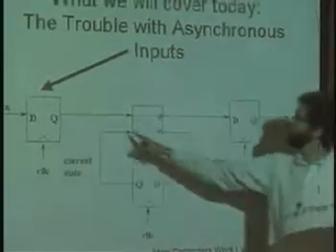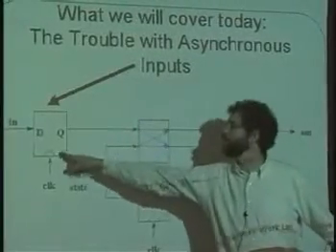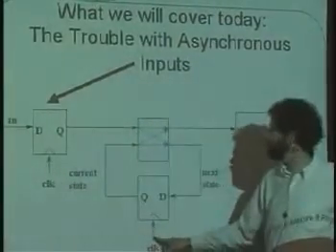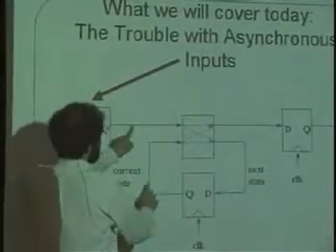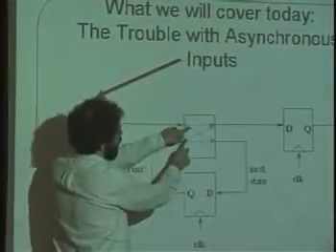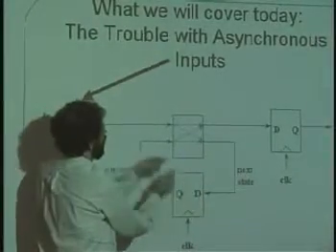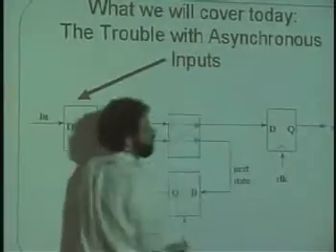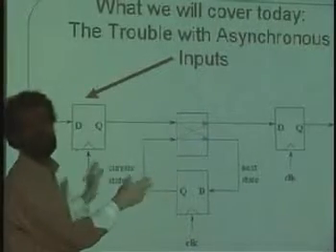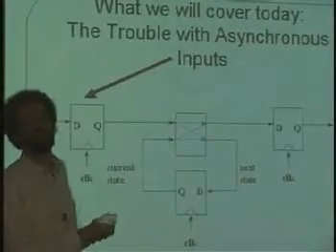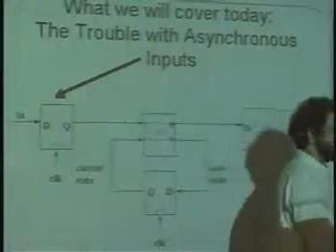So if I have a problem with the timing constraints on this wire being bad, I'll just put a flip-flop there, and since I clock this one and this one at the same time, when the clock goes off on both of these, the amount of time it'll take the data to get here will be the same, and so therefore I will meet the setup and hold times going into here. And the same way going out to this output register over here. I'm clocking all three of these guys at exactly the same time. They're all in sync with each other, plus or minus the clock skew, but we saw how to deal with that before. So this sounds great, except for one thing.